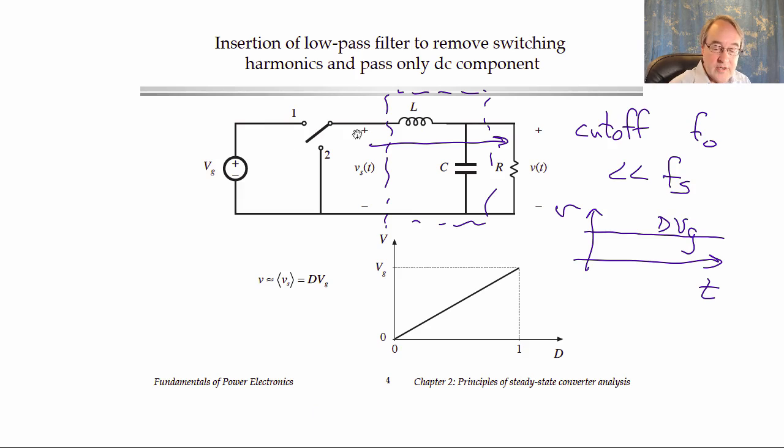So then we've succeeded in building a converter that has very high efficiency and uses elements that ideally are lossless. And not only that, but this DC output voltage is adjustable. By changing simply the timing of the switching to increase or decrease the duty cycle, we can change the output voltage. So we can control the output voltage or make it follow whatever waveform we like.